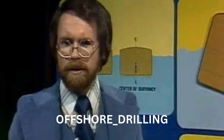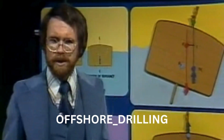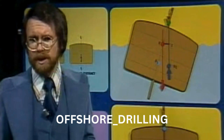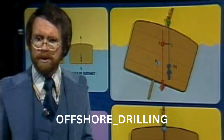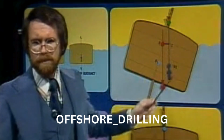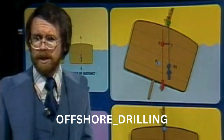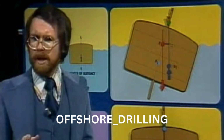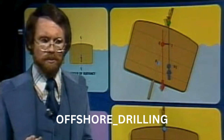It should be apparent that the greater the weight or displacement, the greater the moment, either a righting moment or an upsetting moment. Also, the greater the distance between G and Z, the greater the righting or upsetting moment. So, displacement times GZ equals righting moment.